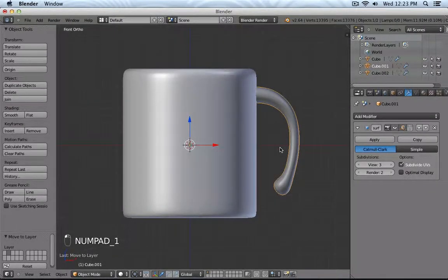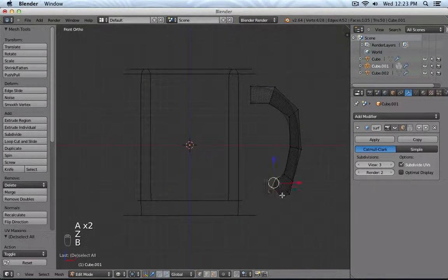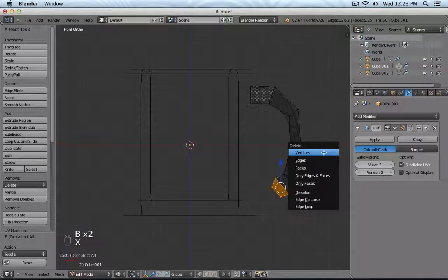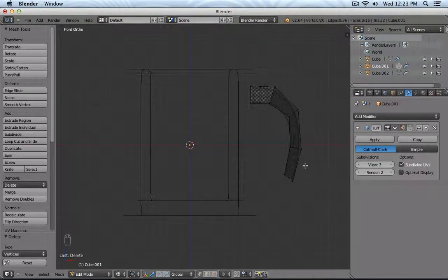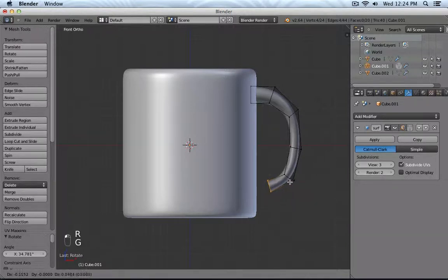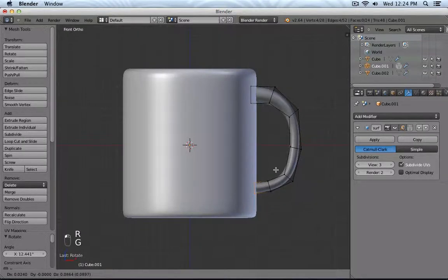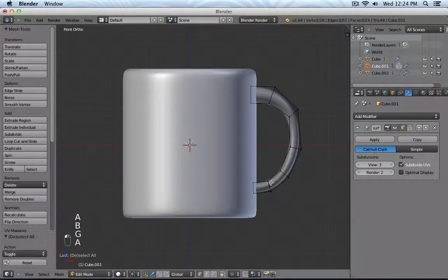And then here I can go into edit mode, maybe select all those points and then say delete vertices. And in this case, that's fine because I would like to remove this sphere shape I created. And then I select all my endpoints again with the B selection tool, press E, and then, for example, finish my object by modeling a surface that intersects with the basic cup surface.